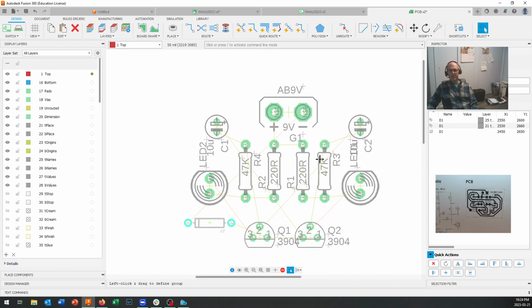So now this might work, it might not work out well. I think he's got it figured out pretty well, but we'll give it a shot and we'll see what happens. Now, don't follow the air wires directly. We're going to do some routing in here. And before we start replacing our nets, the logical links represented by the yellow air wires, with tracks or traces, the physical copper that's going to be going in there, we're going to set some rules up, okay?